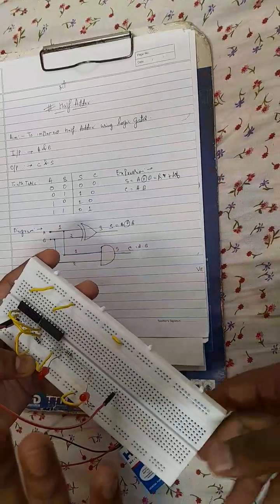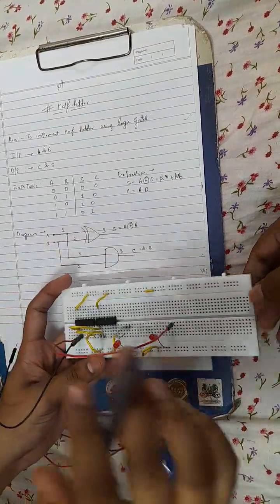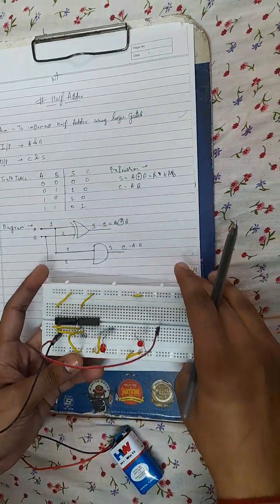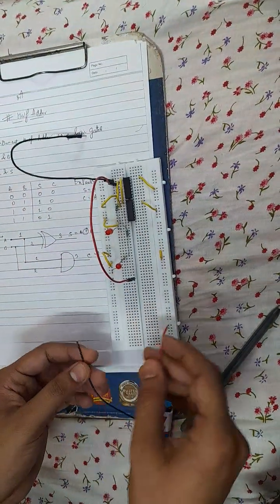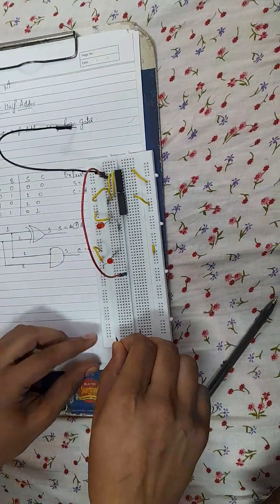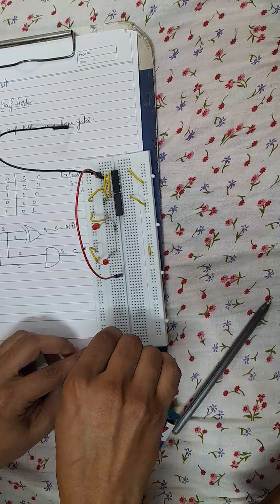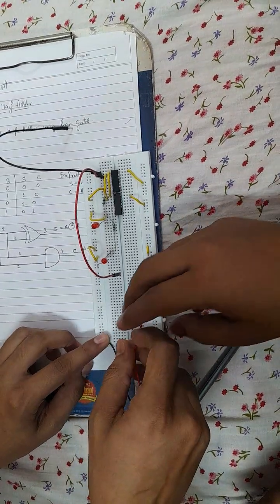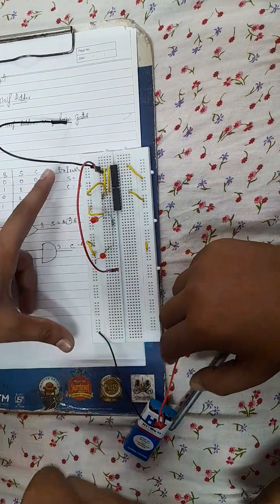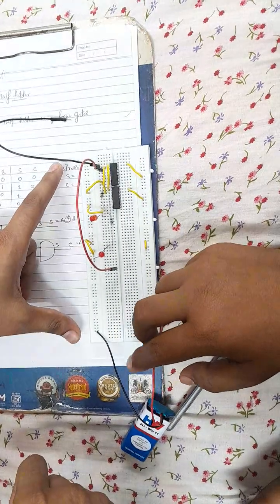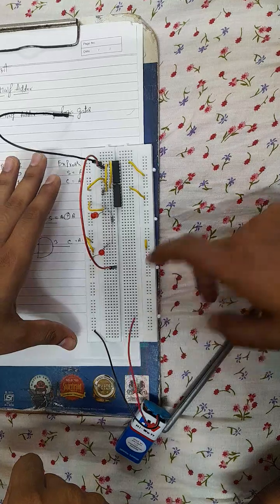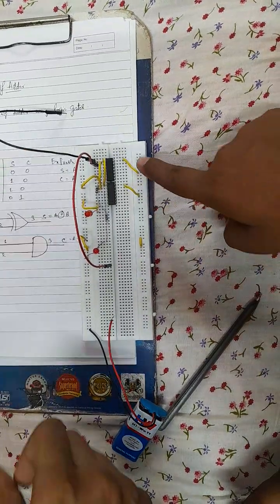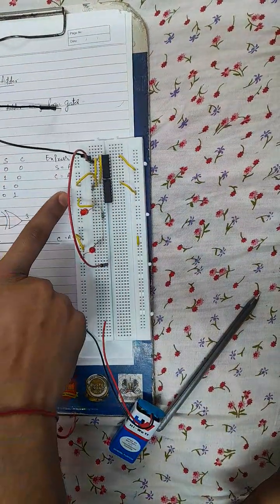Now we will understand how the inputs and everything is working. We have to connect a source battery of 9 volts. Here we have connected it, and we have also connected this so that the whole breadboard rail is common and we can use the whole workspace area. We have also connected pin 14.